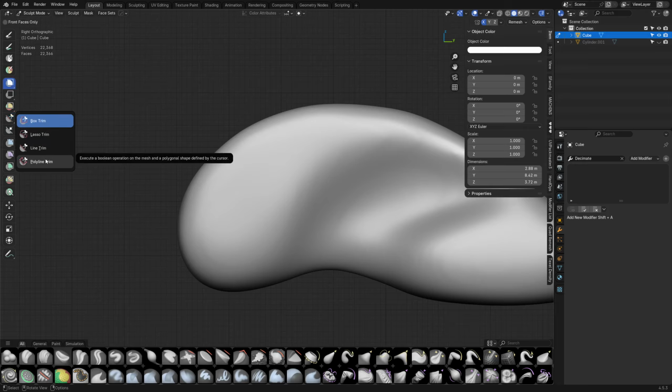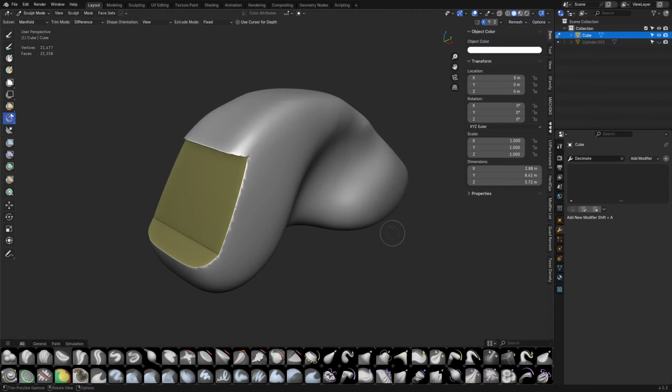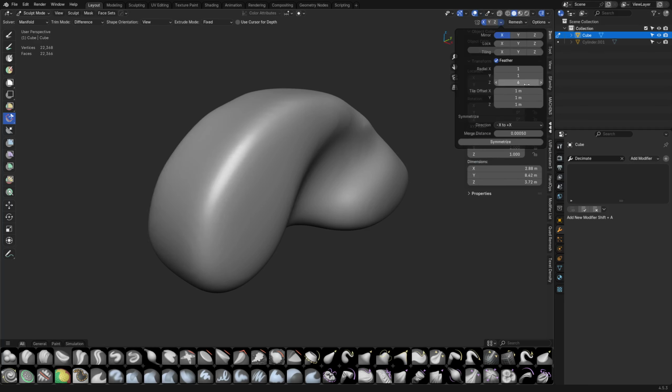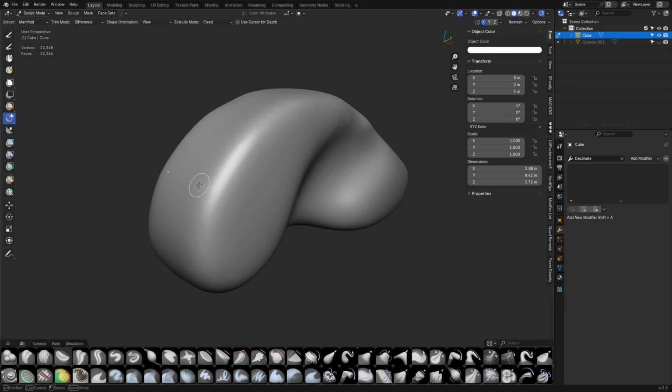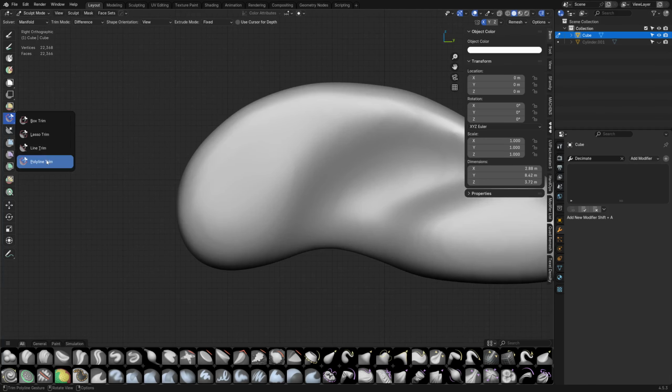But let's say we do a polyline trim. We can click, click, click, drag, click, right? Okay, let's turn that symmetry off, the radial. They're going to change this in a newer version of Blender at some point, where it works on every object. If you set radial symmetry on one object, it doesn't work on all the objects. So it'll be local to that object, which will be nice. But till then, polyline trims, box trims, all this fun stuff's over here for us to utilize.